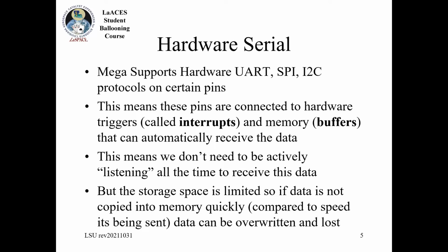Even though all of these protocols are technically serial protocols, when you are talking about the serial pins and serial ports on the Arduino, you are talking about UART pins, the ones that are like the USB. There's also the SPI pins that we've talked about and the I2C pins on certain pins. In particular, the Mega has 4 sets of these UARTs.